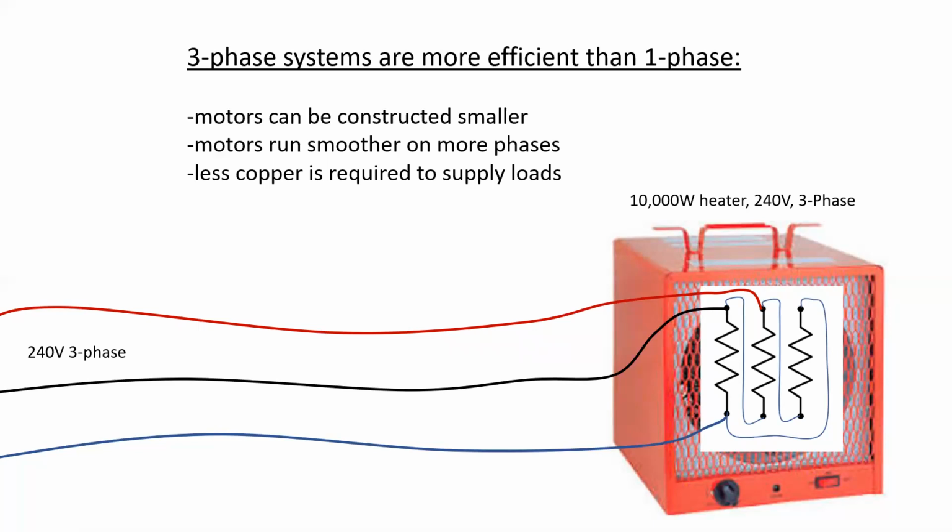And when we do our calculation for the current, we're actually going to get 24 amps. The exact same amount of heat is going to be generated. However, now we have run much smaller conductors, and although I agree we've run one more conductor, the total amount of copper that we have used is far less and is going to be cheaper.